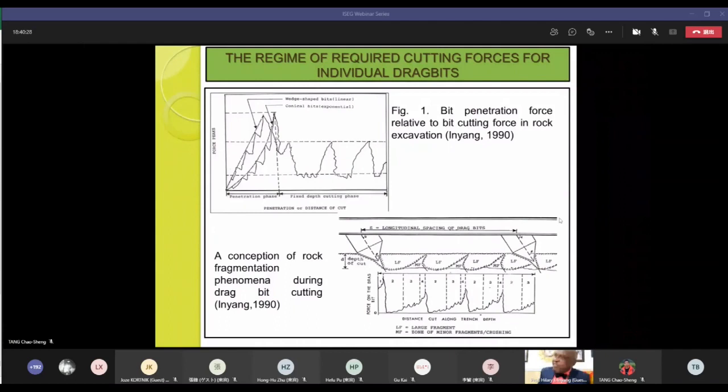And when that happens, if the force, the displacement relationship is plotted, it tends to be this wavy, as I've represented. So typically, when that cutting bit moves across the cutting surface, it will dislodge cracks, as I've seen. You see LP, that's the first one. Once that crack travels to the ground surface, that fragment L is removed. The next one, the bit re-engages with the rock and creates another fracture, and so forth until several fractures are removed.